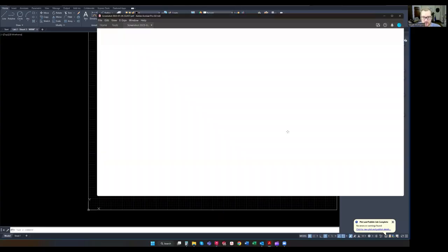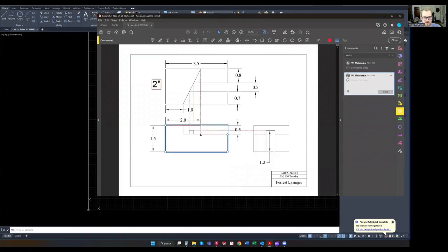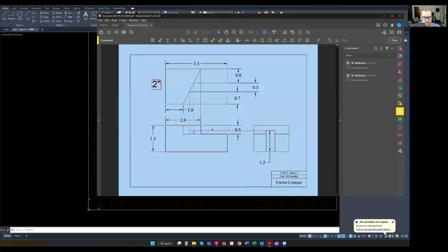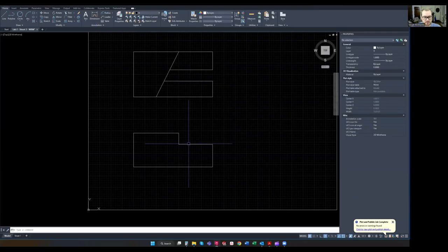Next, looking at our part here. Next, we're going to draw from this point. I'm going to grab my line tool again. From this point, we're going to start here, draw over 1 inch and up 1 inch. We can see how that's lined up right there. Just like that. And then we are going to create this, and I'll show you how to do that. So line tool, L, enter. Starting at this point here. Drag it to the left till it snaps and type 1, enter, and then go straight up and snap it at the midpoint, just like that.